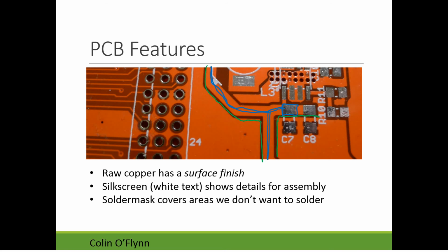So these areas there, we could scrape it away. It's just a thin coating like varnish or paint or something. You can use a knife and scrape it away, and it's just raw copper underneath that.